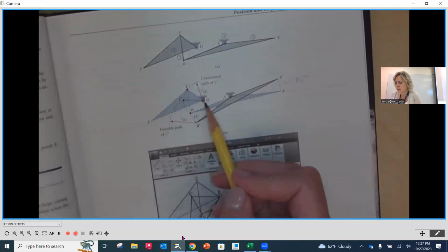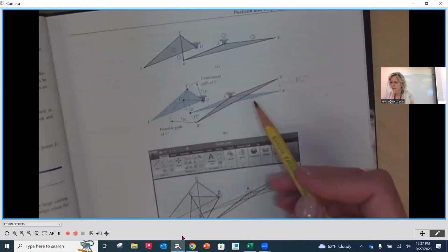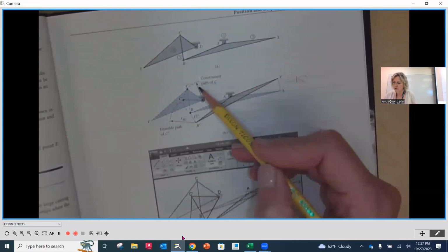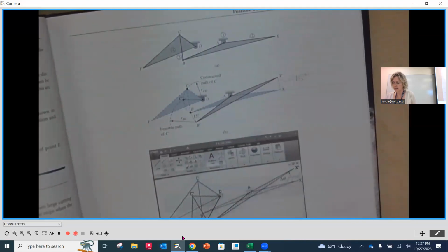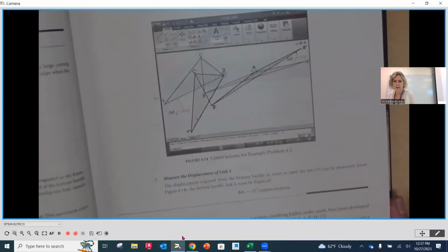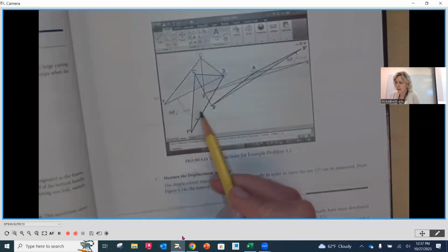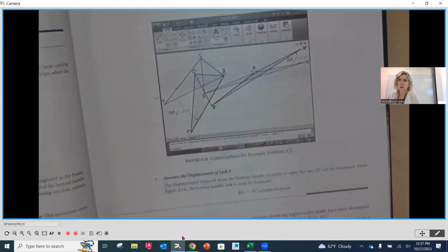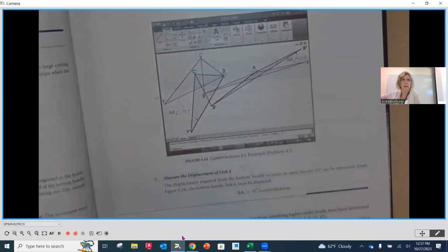So anyway, this is going to represent that initial position of our handle. And then once we move this 15 degrees, notice that we strike the arcs to show the paths and the differences. And then down here is going to represent from its initial position, which was Y, to get to Y prime, this is now going to have to open up a total of 34.4 degrees in order to get 15 out of this side, okay, to open that up.